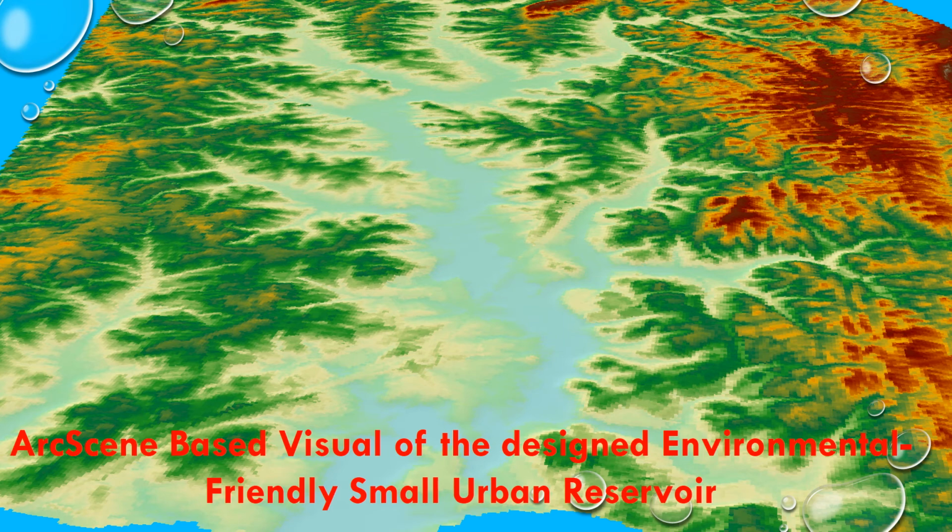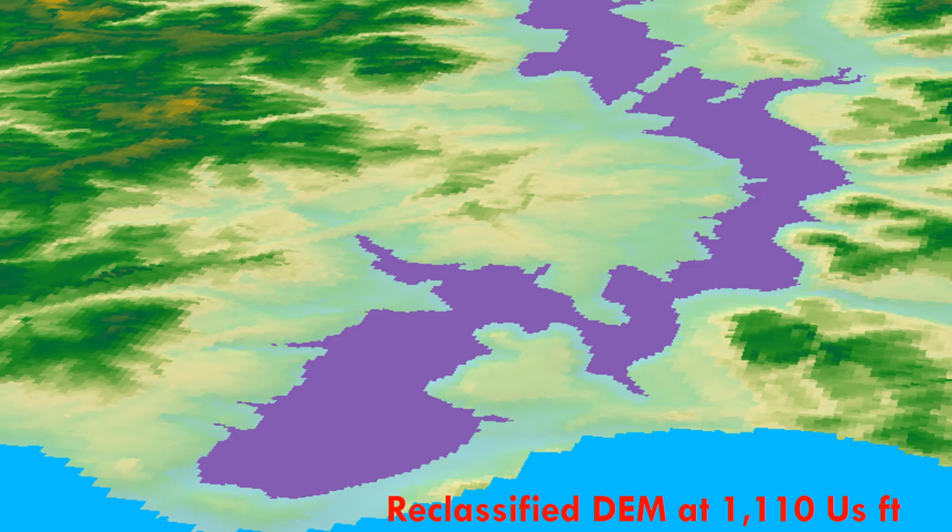You can see the blue area, that would be our reservoir inundation area. And this shows the reclassified DEM at 1,110 US feet. That is our pool level plus 1 foot of extra that we keep. So that means all these areas will be inundated.